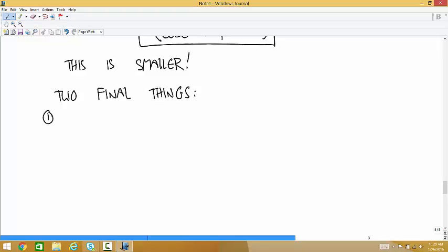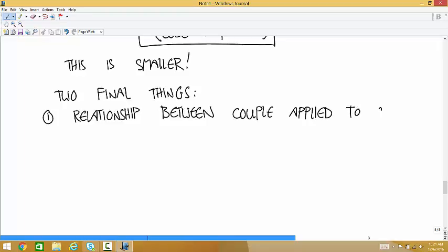You don't do it by applying a force Q. So we have to figure out a relationship between the couple applied to the screw and this fictitious force Q. That force Q is fictitious because that's a force we're imagining applying to that block, and that block is part of the thread, right?